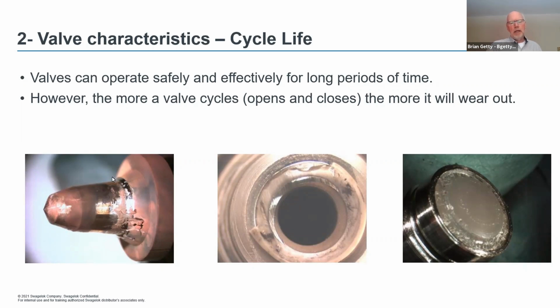This is a needle valve, okay, a regulating stem tip needle valve. It has a metal to metal seal, and you can see that by the polishing that's happened in this area here. But just look at some of the wear now. The length of time that this valve was in use, I can't tell you, but I'm just showing you some of the potential wear that you will find in your valves.